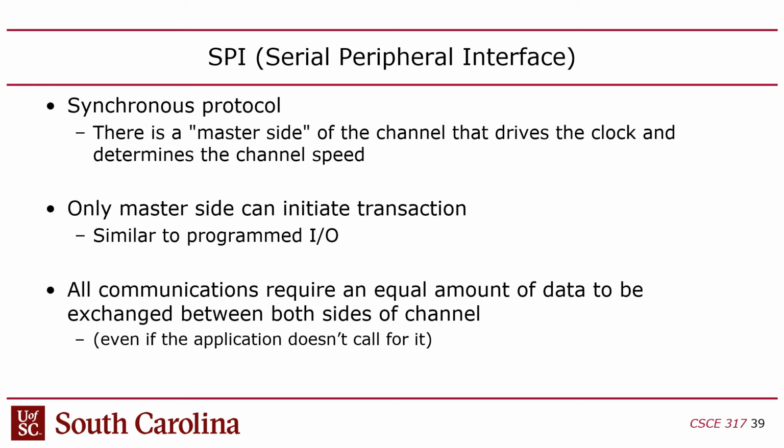And there's a 4th one too, called slave select, that is used to basically activate the channel, turns the channel on. It distinguishes between the channel being idle and the channel being active. So those are the 4 connections: clock, data one way, data the other way, and then the turn on signal. Okay, so SPI is a master-slave style interface where you have a peripheral that's designated the master in the sense that it's the only one that can initiate communication, and the slaves are the endpoints, and they're the ones that respond to requests for communication by the master.